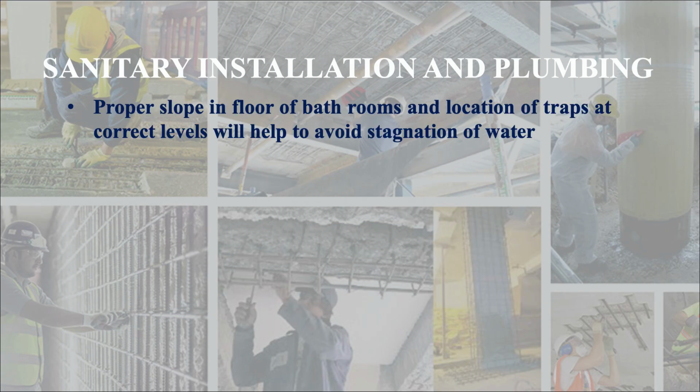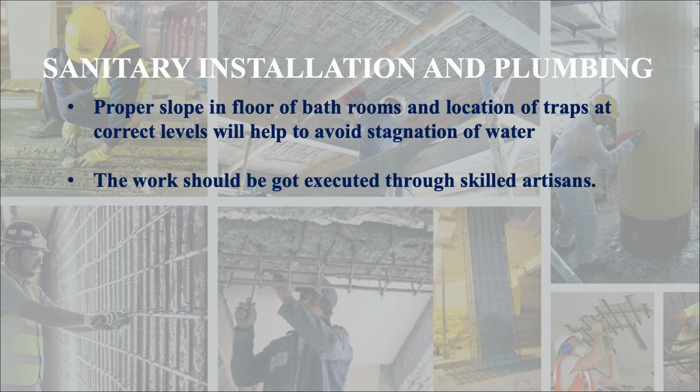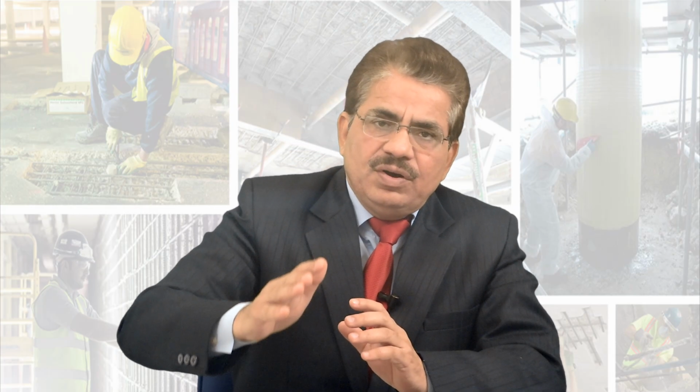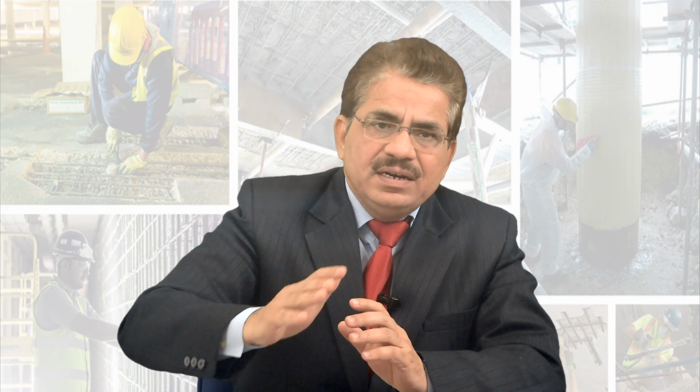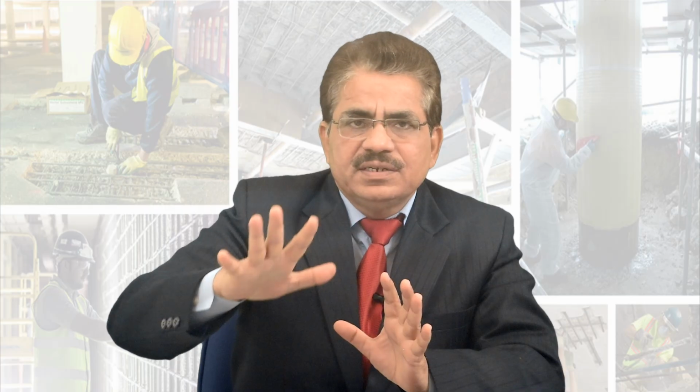Proper slope in the floor of bathrooms and location of traps at correct levels will help to avoid stagnation of water. The work should be got executed through skilled artisans. This is very important. The artisans or workmen should be skilled for the fitting and fixtures in the various plumbing operations.